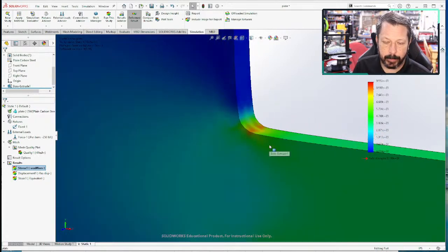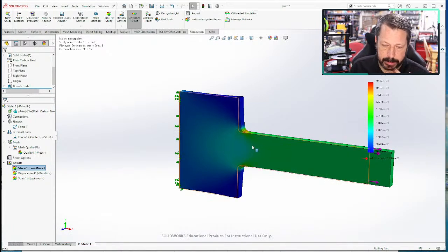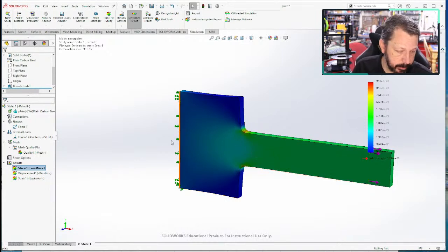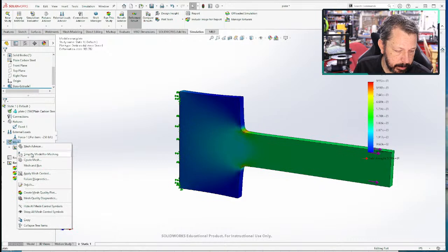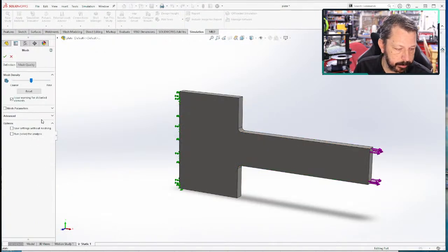So I'm relatively confident that we're doing the right process, both by hand, and we could probably do a better job on the finite element part, but we're accurate. We could go in here and go to our mesh and remesh the thing. One thing we could do is just have more elements, making it a finer mesh, meaning they're smaller.